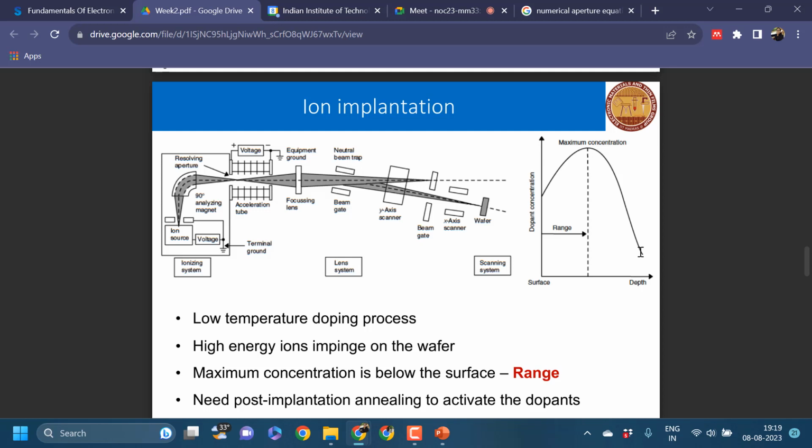A light sensitive polymer, which means that it can change its structure. So there are certain polymers that undergo cis trans transformation, etc. on light exposure. So such kind of a polymer will be there. A solvent will be there. It is usually added to thin the resist, and it will be removed by the soft bake process after application. Then we have what is known as a sensitizer that controls the chemical reaction during exposure. And finally, we have additives in the form of dyes.